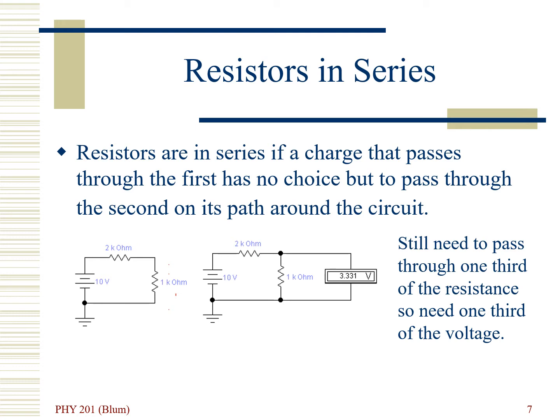And then we look at the voltage across the 1 kilo ohm resistor and the total resistance was 3. If we did an equivalent resistance of 2 and 1 in series, we would add them and get 3. But the voltage across just the 1 kilo ohm resistor is then 1/3. We need 1/3 of our energy for this, and so it is 3.33. So we're getting a partial voltage. 10 in this case is our high, 0 is our low, but we're getting some intermediate value based on the values of our resistors that were in this case in series.